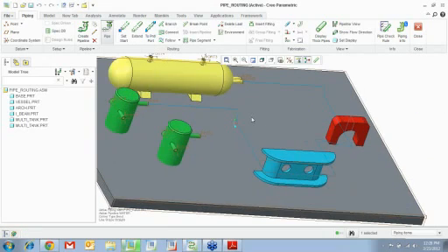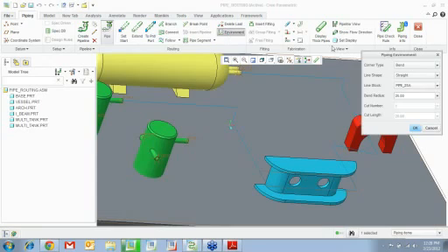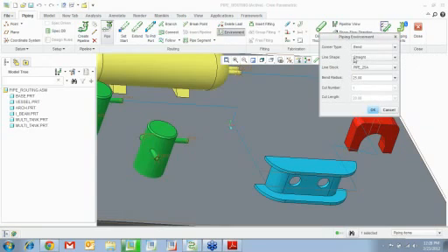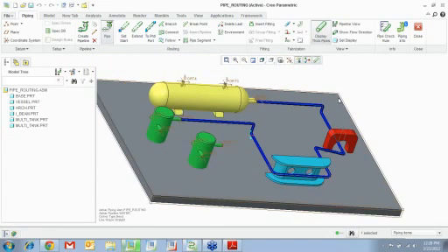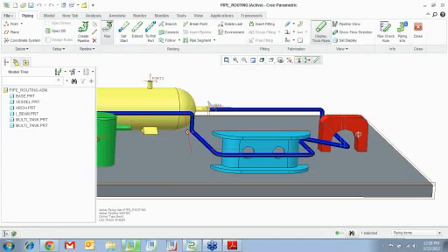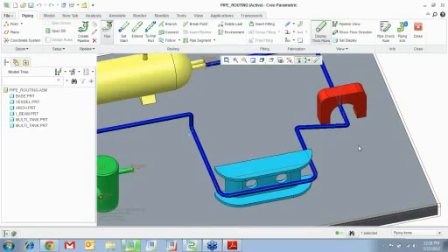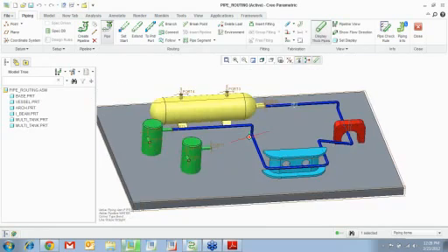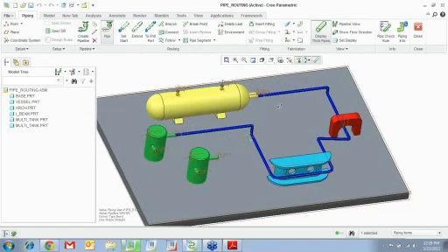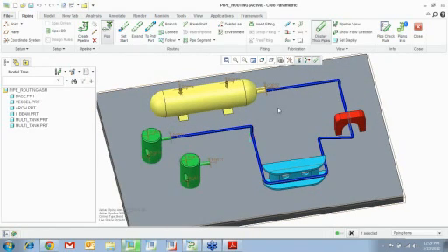You notice all your bends are automatically added. They are added automatically because the environment that you set in is bend and the lines type is straight, and that's your bend radius. You have options to choose from any of the 4. This was my default, so I let it pick that. So now you can see display thick pipes. You can see how your pipe goes. Right? So now, that's how you would go ahead and route pipes. I've tried to show you pretty much most of the options right here.